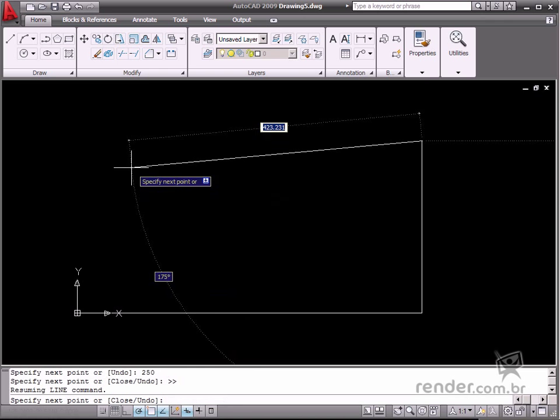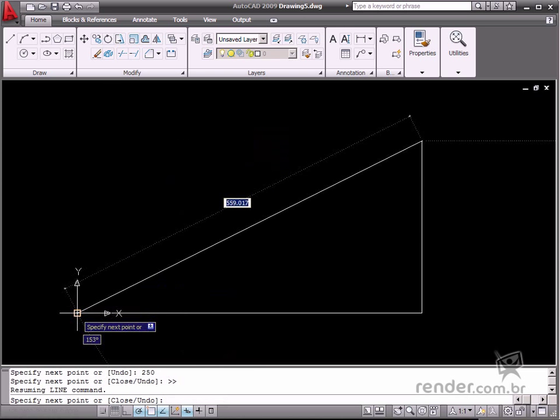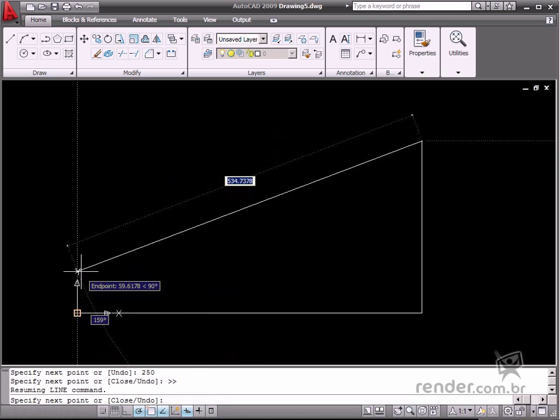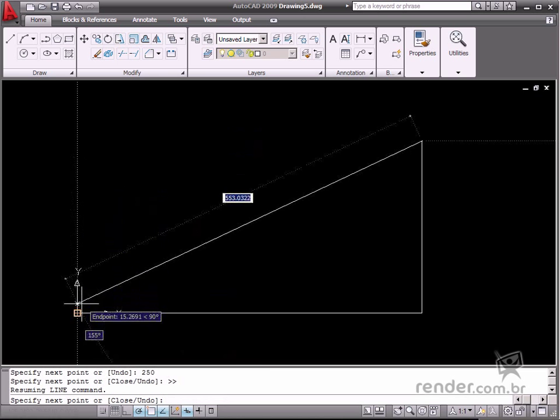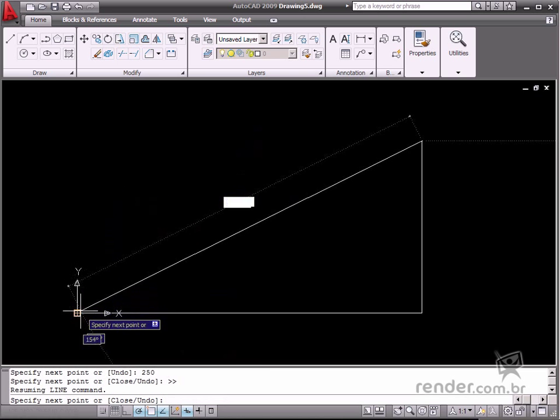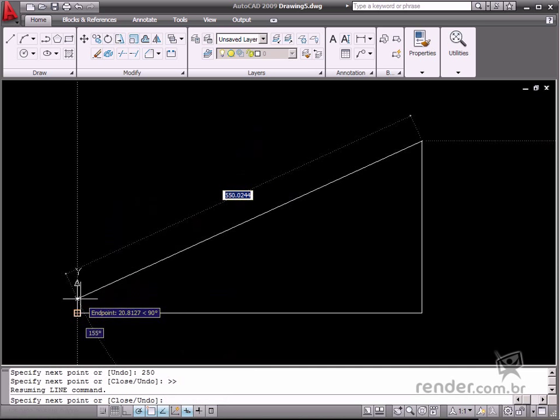After the Line tool is enabled, move the cursor to the starting point of the geometry. Notice the symbol which is now displayed to show you the selected point. This captured point is the endpoint, which in this case is the end of the line entity.